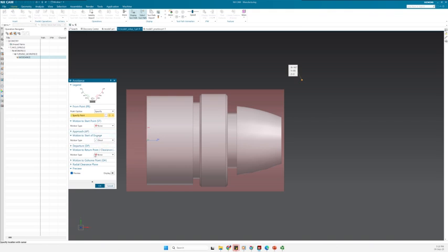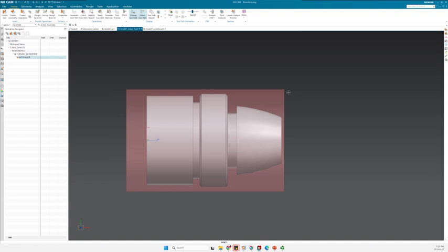Then after that, I have the go to home point. I will select first to de-engage axially and then radially. So axial, radial. And then I will say to define the same points. And now I have the points here. And then I can also define the geometry for a plane that I can consider as the plane that would be for the spindle.